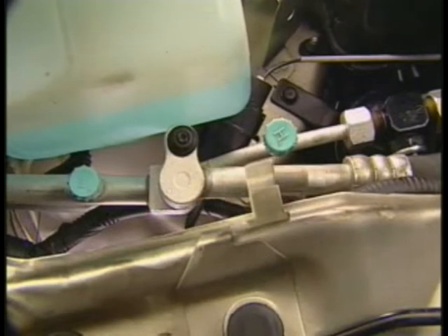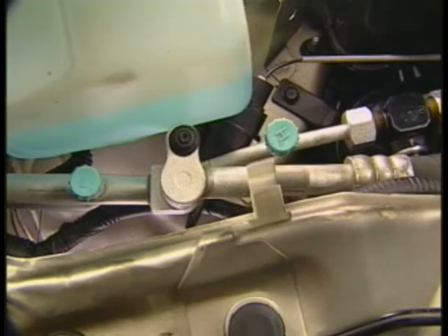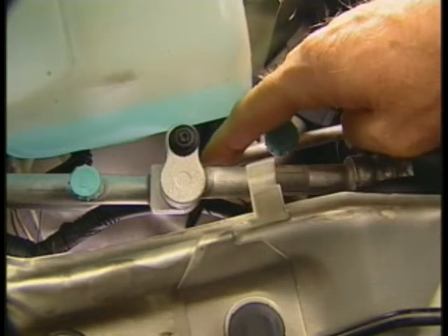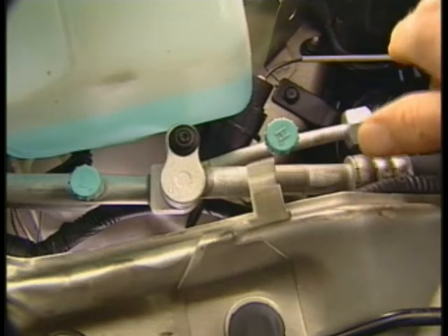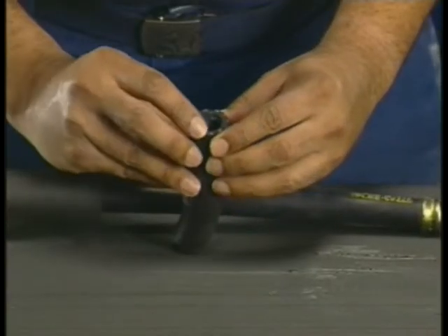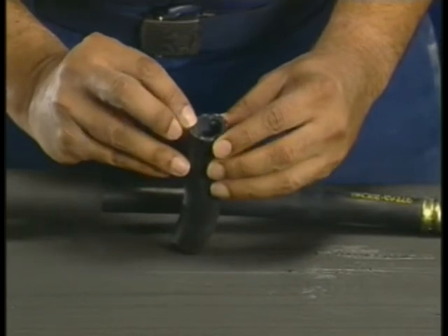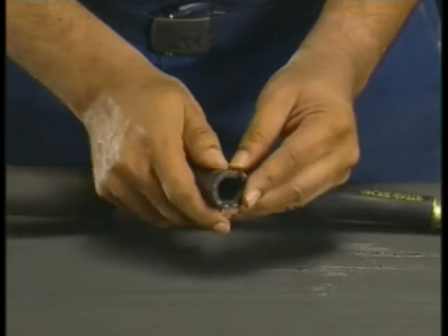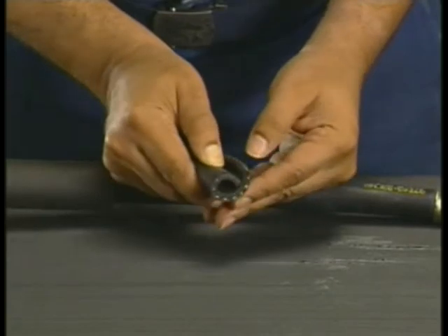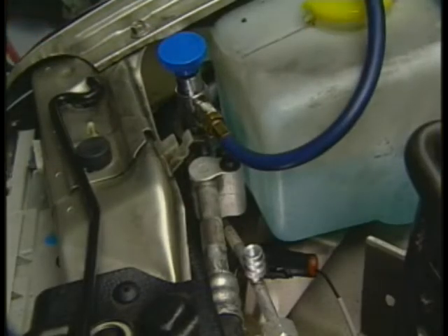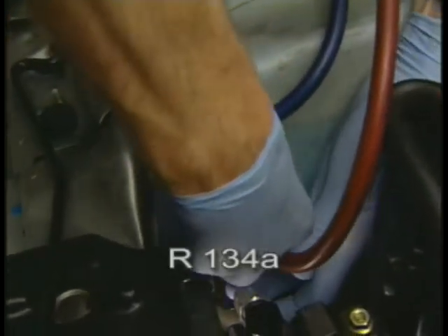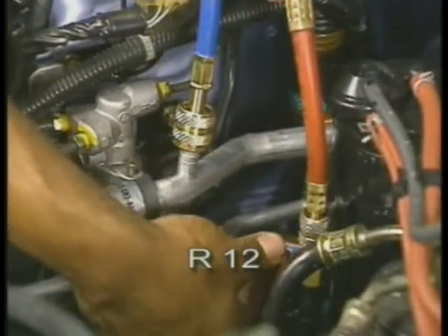The refrigerant lines connect all the components of the air conditioning system. Refrigerant lines can be made from copper, steel, or aluminum. Hoses are usually made from synthetic rubber covered with a nylon braid for strength and have an inner nylon lining to prevent system contamination from degrading the rubber. The types of hoses, fittings, and the O-rings that are used to seal them differ between systems that use R134A and systems that use the older R12 refrigerants.